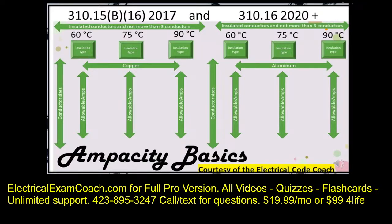The first distinction we want to make with this table is that it's actually two tables. On the left-hand side is going to be for copper conductors, and on the right-hand side is going to be for our aluminum and copper-clad conductors.